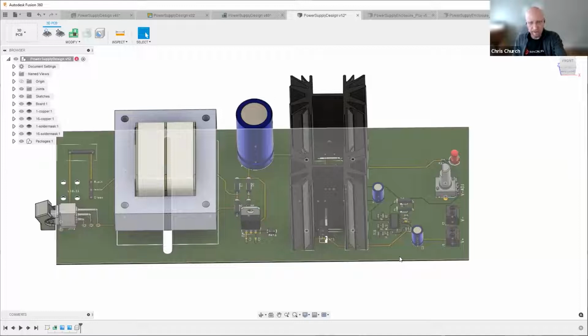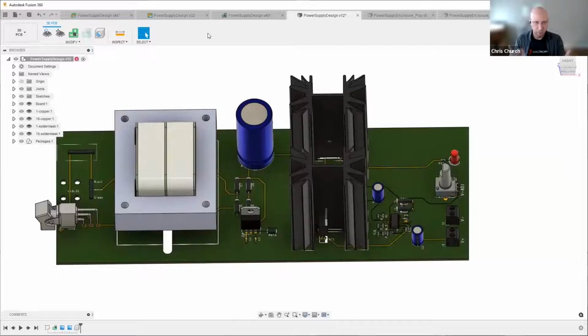But here we're going to want to add test points because having someone plug in those wires is going to add a lot of cost. We need to protect the operator from that. So we would design this test fixture for you, and we'd ask to add test points on the left side for the AC input and test points on the right side, both for the DC outputs and that V-adjust potentiometer. Because we're going to want to test a couple of things, right? One is that as we make changes to that potentiometer, the DC levels change the way we're expecting, but we may want to test also that the potentiometer is within spec.